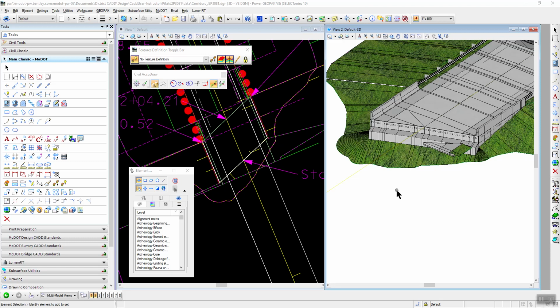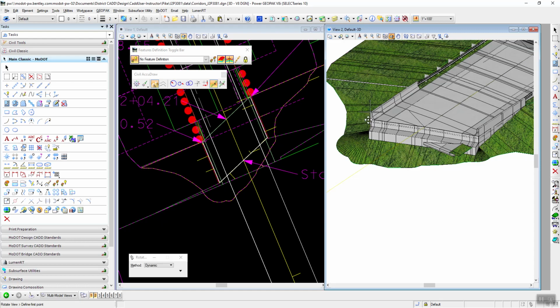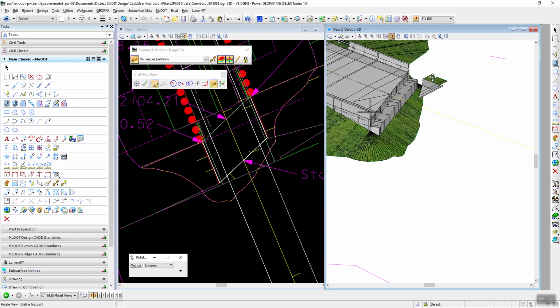In this last video for the bridge indent layout exercise, we're going to focus on clipping out certain elements. For example, we did a corridor clip earlier, and when we did that, we clipped out the mainline corridor, and we used the indent corridor to do the clipping. But when we did that, the end bent corridor wasn't big enough, and we have this little piece hanging out right here. And so we're going to show you how to create a clipping corridor that will clip that out.